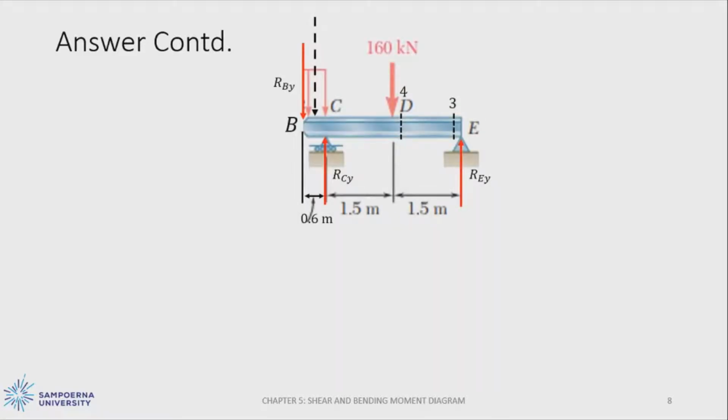If in the previous one we starting from the left to the right to create the partition, now in the second section of the beam we start from the right to the left. So we start from the third partition is right before it is reaching point E, or in the left part of point E, and then the second partition is on the right part of point D, or it is called as D2 because it is on the right part of point D.